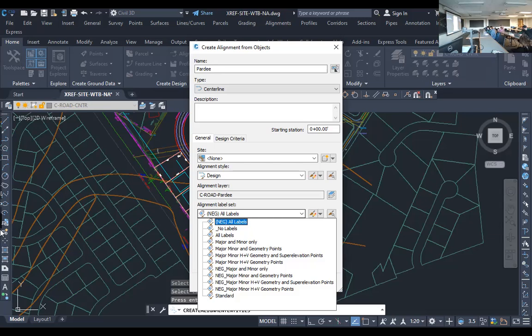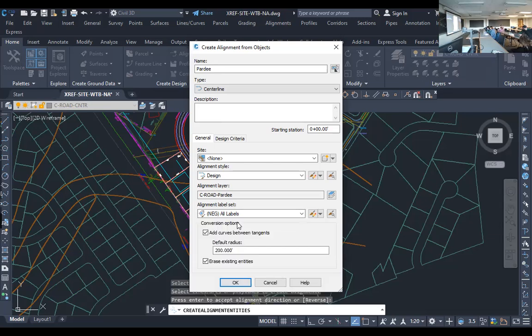Okay. If these aren't in the drawing when you go to do it, then you need to insert that template drawing that I have. We started from scratch, and that is in. Everybody know what I mean by that? Just need to insert it as a block, and then those styles will appear.